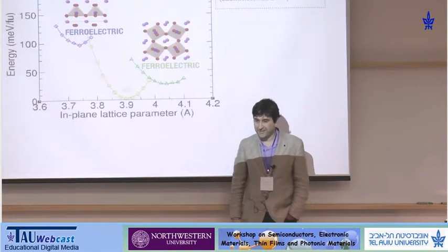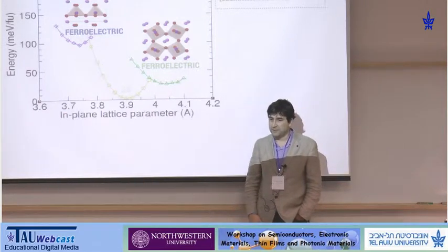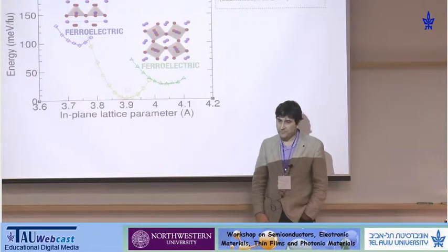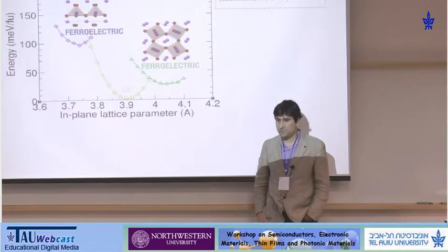Okay. I have a question about the compound with scandium, and it's just curiosity. With a colleague of mine at Northwestern, David Dunand, we've been working for about 15 years on aluminum scandium alloys because you form an Al3Sc, an L12 structure, aluminum-3 scandium, and it has a very high melting point, so you can produce high-temperature alloys of aluminum with it, but scandium is very expensive. So we dope it with even-number rare earth elements that are less expensive than scandium, and they substitute on the scandium sublattice, and it's really useful, the alloy, except that scandium is expensive. So I'm wondering, this phase that contains scandium, what are its unique properties?